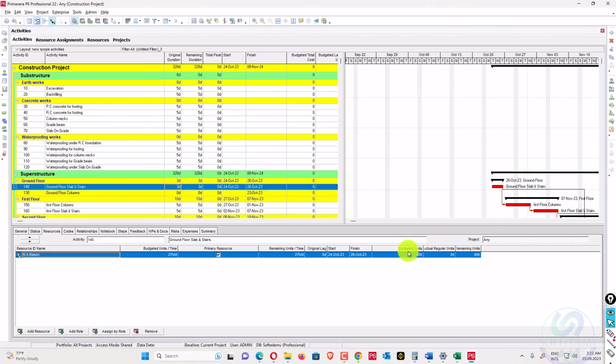So these are direct, and you also have to calculate the indirect, because indirect resources are the most affected during claims, because indirect manpower get salaries on a monthly basis. So it is more significant than your direct resources. So this is today's content related to productivity rates, resource allocation and resource loading in Primavera P6.